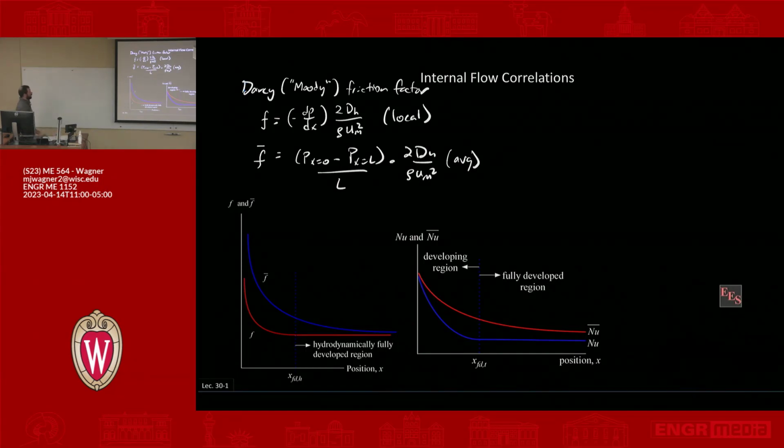Okay, so some similarities with the coefficient of friction. It's always with reference to the momentum of the fluid, but here we're looking at um squared, right, as opposed to u infinity squared. So that's the momentum of the flow in the constrained space, and then you're looking at dP dx as something that's present there as well. Okay, so that's on the momentum side.